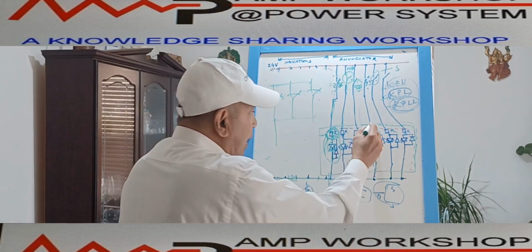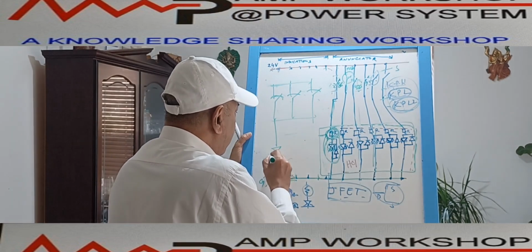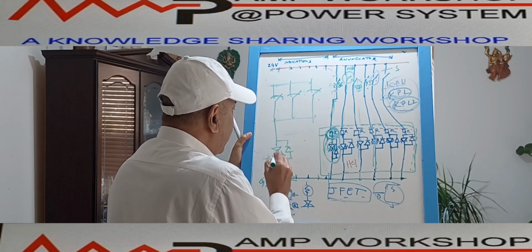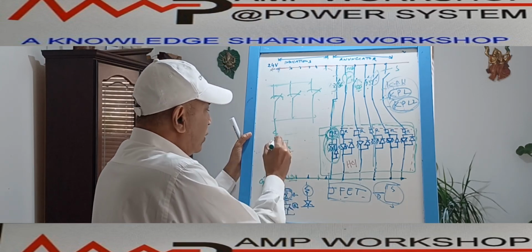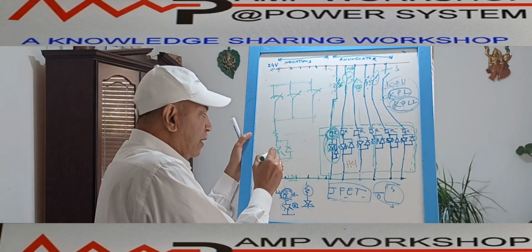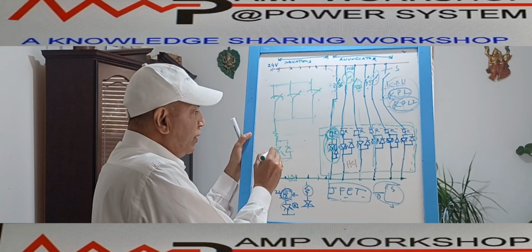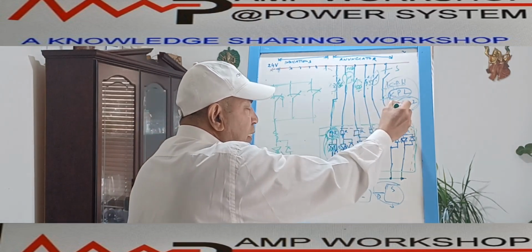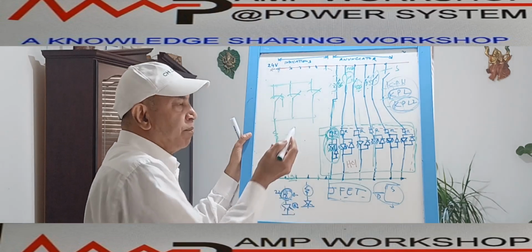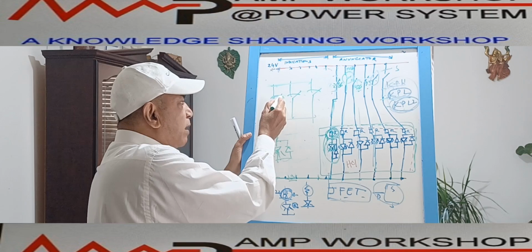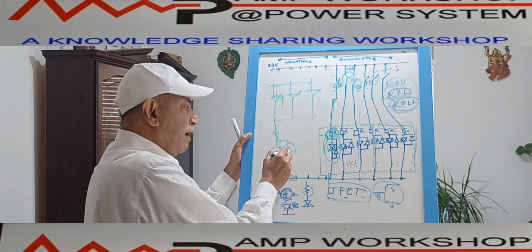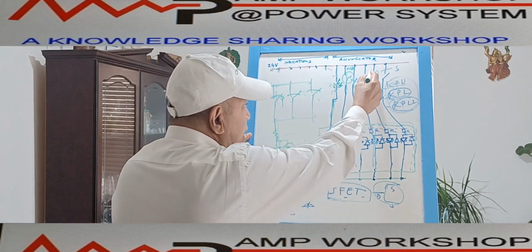So no signal is coming to the lamp. There is a lamp over here. This is a lamp, and this is a reverse biased zener connected over here, and this is a balance resistor. In this way it is working. But the moment any of the switches operates, when the pressure is abnormal, this NO contact becomes NC and the corresponding lamp will glow, and the reverse bias diode will be in parallel. So this way we can monitor this thing.